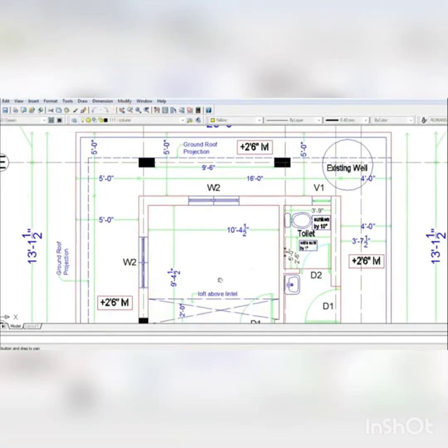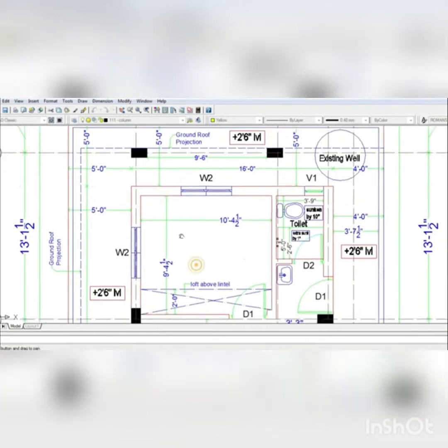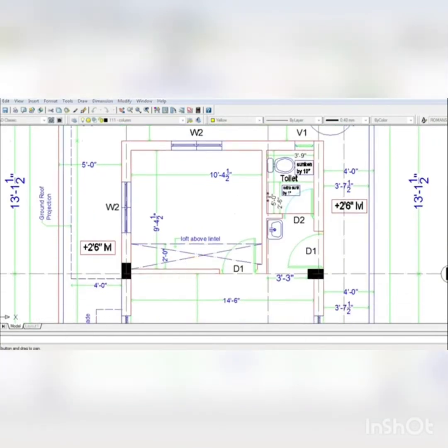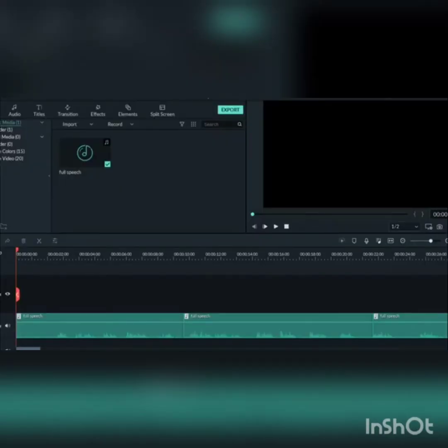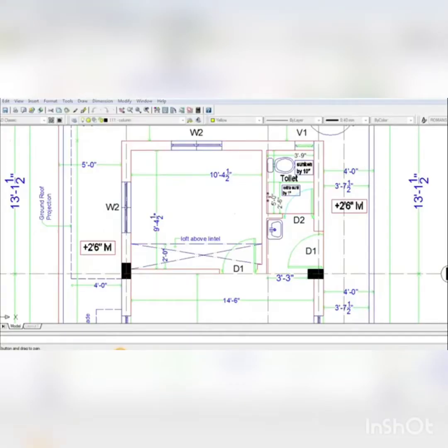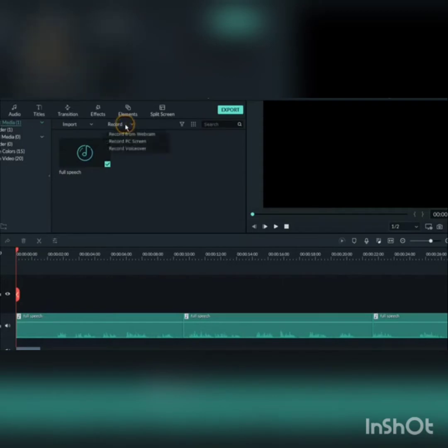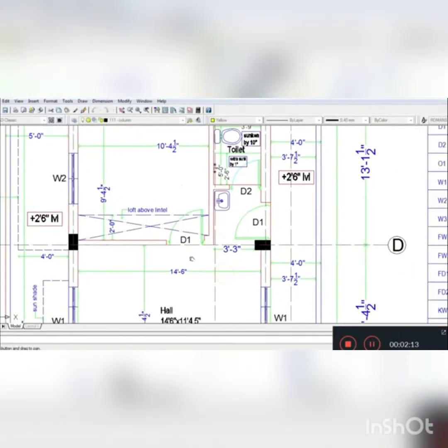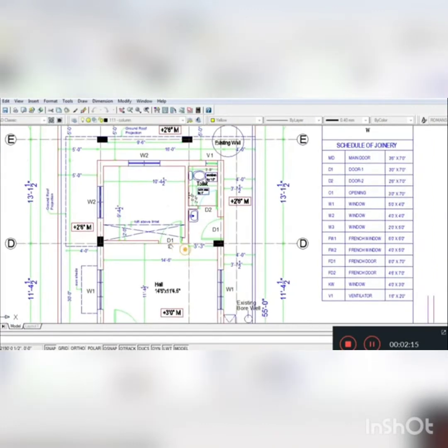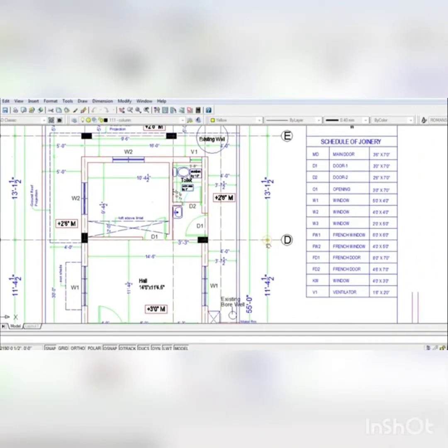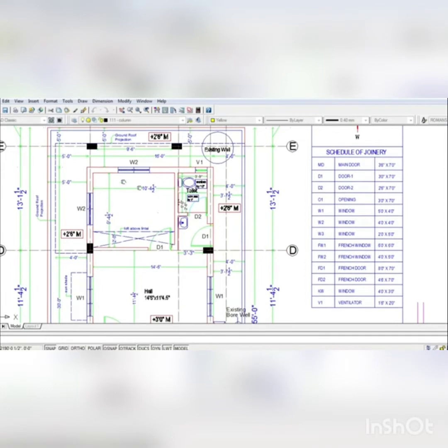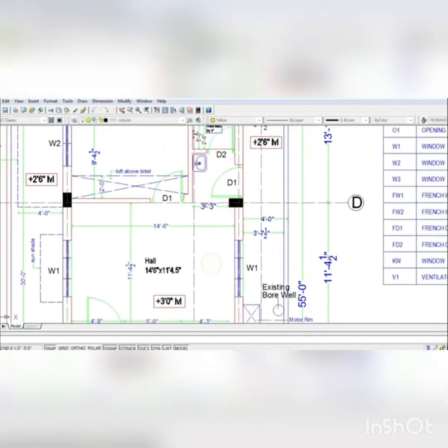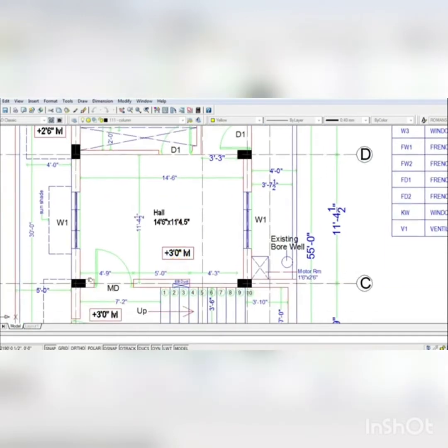After the centerline drawing has been incorporated into the floor plans, the next step is to provide the room dimensions, each room's dimensions. Wherever the offsets or cross walls are coming, we have to provide the necessary information so that by seeing the dimensions, they can mark the walls for construction. All necessary dimensions of the rooms are to be given for constructing the walls.